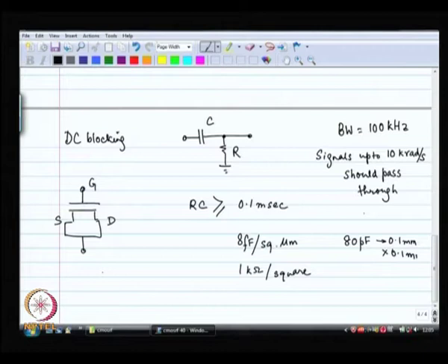That is a very large amount of area that you have used up in building an 80 picofarad capacitor, 80,000 femtofarads. So, 10,000 square microns, so 100 microns by 100 microns. So, that is 0.1 millimeter by 0.1 millimeter, that is a fairly large sized capacitor.